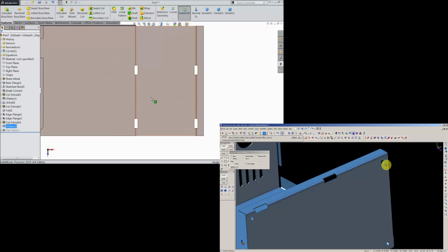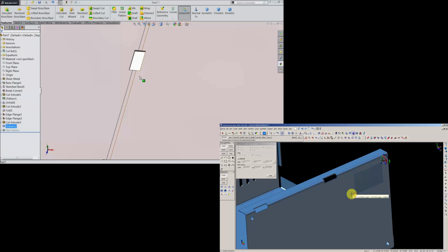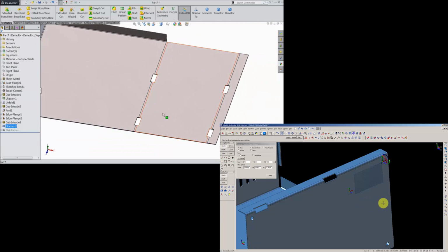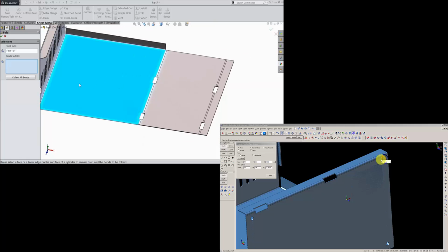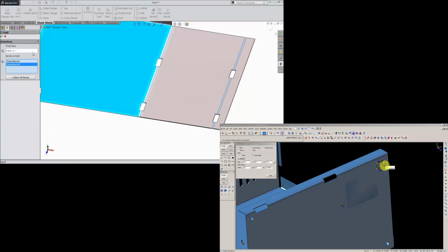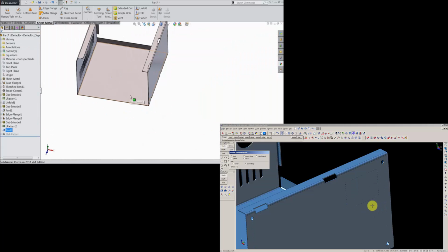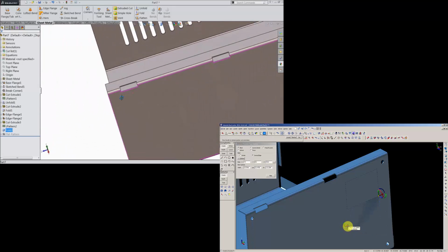Select. Okay. Now see this corner, this cutouts created. Now we will unfold. Just try to unfold. So select fold. This fixed surface created, just select the edges, one edge and this two edge. Select OK. Now see our geometry is here created and unfold.